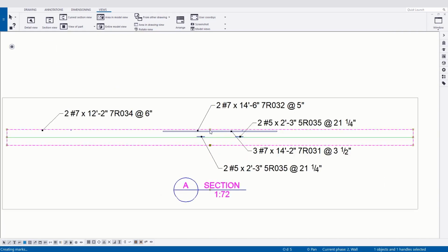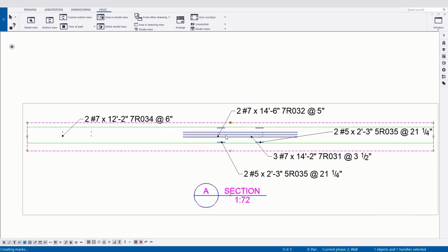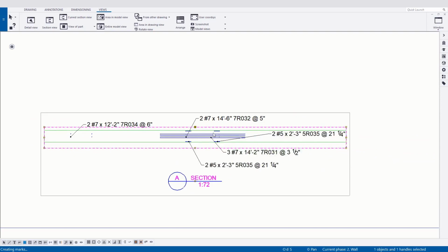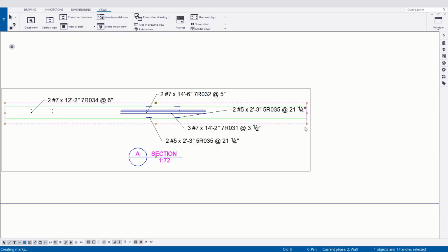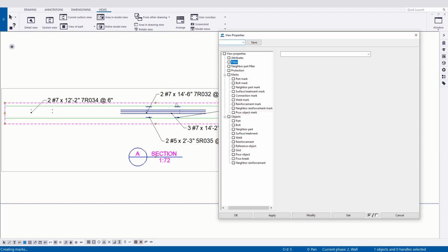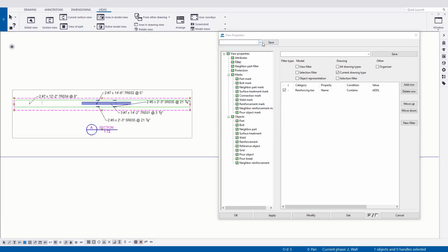Now it's using some saved drawing settings. If I expand the view extents, you can see now it's grabbing some of that bar. It is only showing the additional bar, if you notice, which is not what we want to do here. So it's quick and easy to adjust, double clicking on the view settings. And again, this is going to use the last applied view settings. Now you can always use any of your own view details here. Simply, I'm going to turn off that filter so we see the bulk of our reinforcement. You can delete that row and select the view and hit modify.